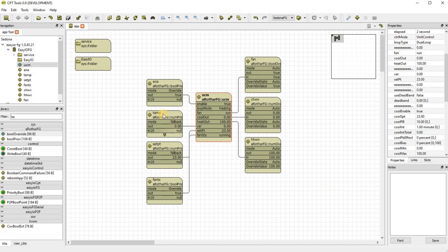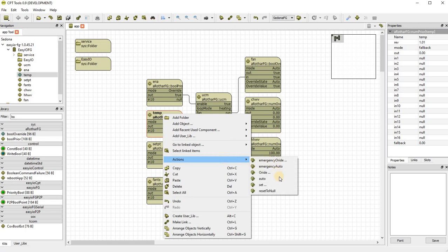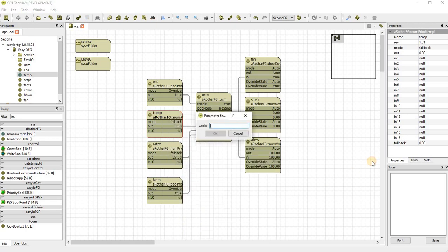All right, let's unwind our loop. Let's set it to, I don't know, 100, just to drive it into cooling, right? You can see the heating output will reduce, and it's not until it goes to 0 that the cooling effect can take over. It changes the cooling, winds up on the heating loop.